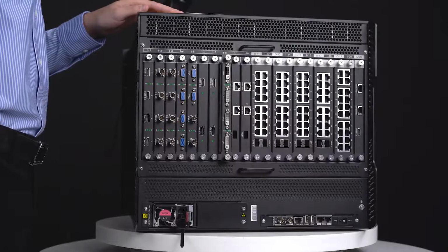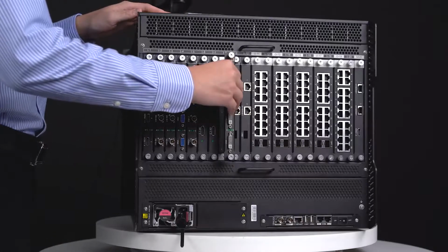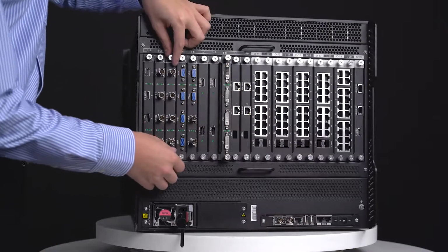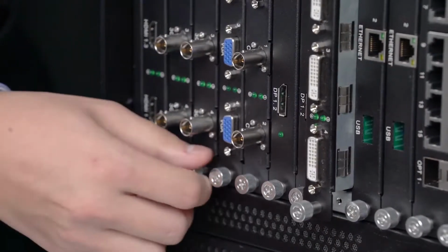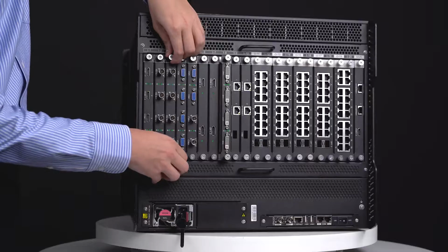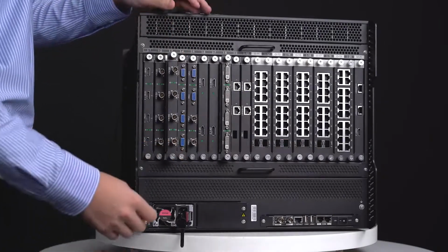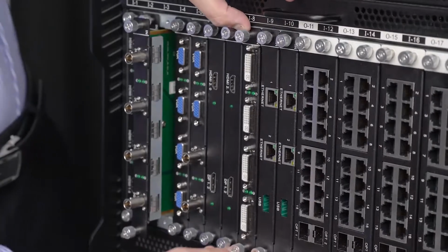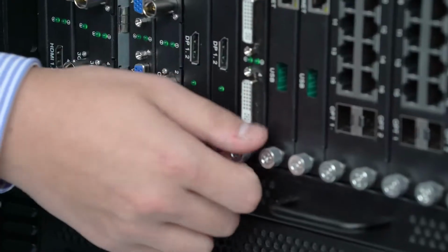As I mentioned, all of the daughter cards are modularized, which means you can plug in or pull out any one of the daughter cards whenever you want. Let me show you how to do this. For example, this one. Turn the bolt screws anti-clockwise till they pop out, so that you can pull them out. On the contrary, if you want to plug in, you're supposed to plug the card in to the end and then press the screws a little bit before turning them clockwise.